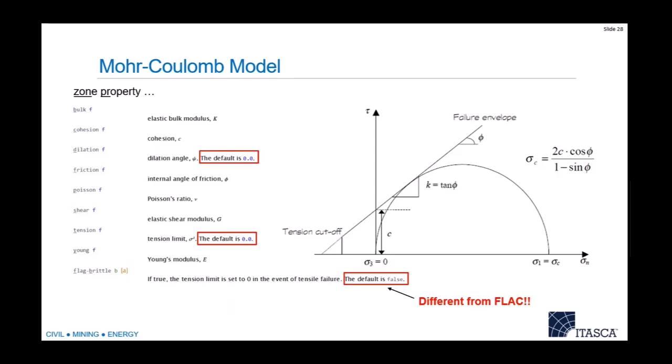So you can imagine if you have high normal stress and a low shear stress, you're safe. You have a high shear stress and a low normal stress, you're in the failure zone. You never actually get to this zone, right? What happens is your stress increases, you hit this envelope, and you move along the envelope. This is a non-admissible state up here above the line, right?